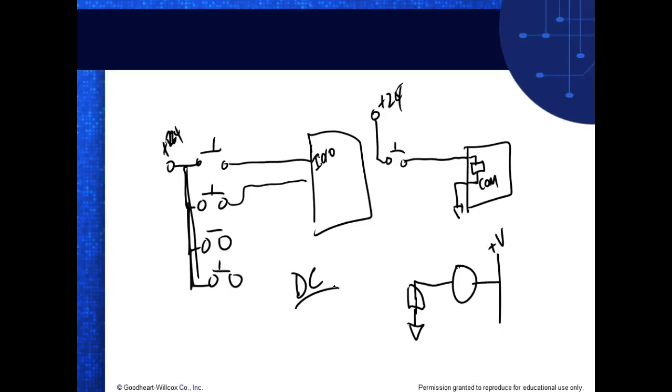The 1100 and the MicroLogic, they've got inputs, they group them in two groups. So you can set up one group for sinking and set up the other group for sourcing. And that's also true on the 1100s. Both of them have relay outputs. What does it mean, relay outputs? Everyone's got their own common. So literally, if you've got the MicroLogic 1100 or the MicroLogic 1000, you can set up input 0 as sourcing. You can set up the other one as sinking, or you can use AC, which is really, really neat.